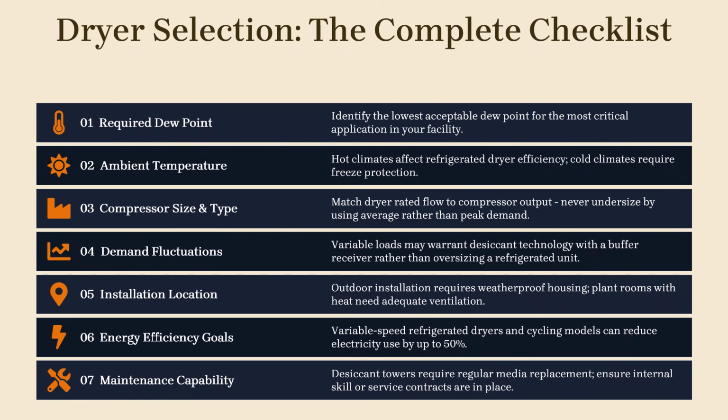Selecting the right dryer involves much more than matching it to the compressor size. A complete evaluation of operating conditions is necessary to achieve reliable and efficient performance. The process begins with identifying the required dew point for the most critical application in the facility. Ambient temperature also plays an important role, since hot environments reduce refrigerated dryer efficiency, while cold climates may require freeze protection.